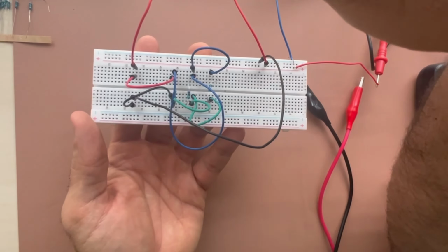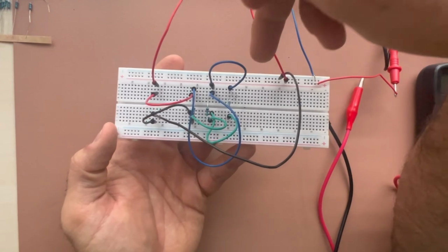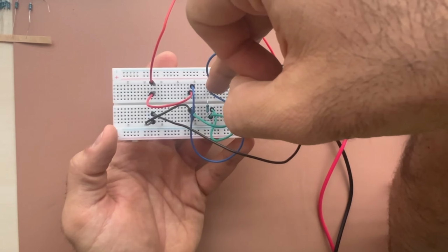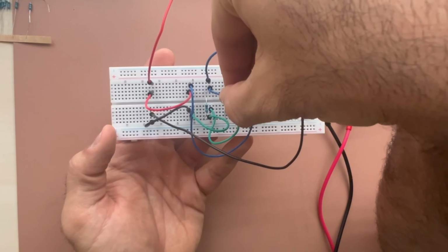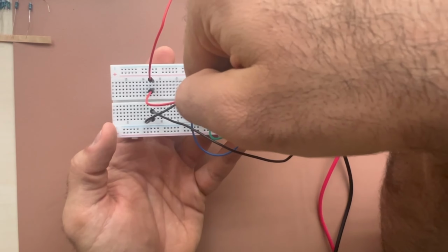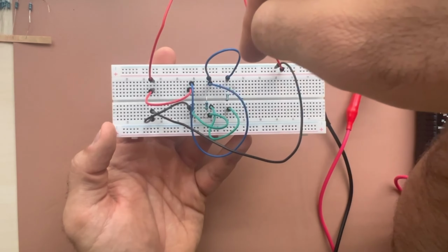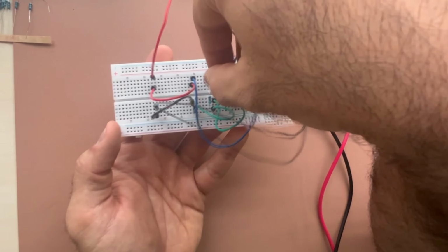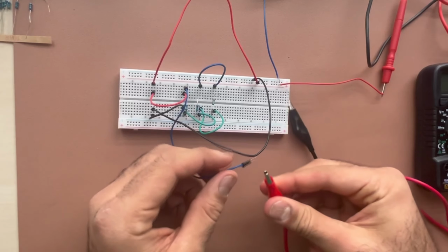But here's the main problem, because at this point, if I disconnect this part, the current that I have from this guy is going to affect this guy as well. So it would be better, rather than doing that, to either find the voltage of my resistor divided by the resistance that I have, or check what would happen if instead of disconnecting that, I disconnect this guy. If I do that, I'm probably going to have another issue.